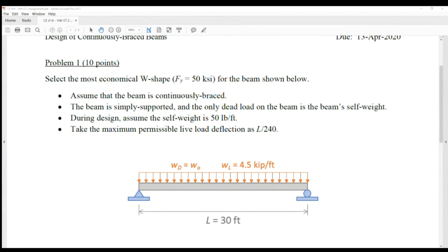So are you saying that if you assume like 100 pounds per foot and the section ends up being like a W14 by 22, that if you assume too heavy a value, could your section not be as economical? That's possible, but in building design, there'd have to be a big discrepancy between your assumed self weight and your actual self weight for that really to be an issue.